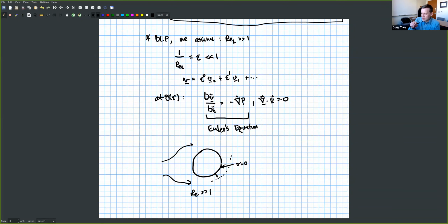And in cylindrical geometry, you can see that this doesn't happen. We talked about this if you took my undergrad fluids class, and hopefully somewhere in fluids, about what's called D'Alembert's paradox. It turns out, and we'll talk about this in a second, that when you solve for this outer region and then try to calculate the drag force, it is 0. That's because there are no viscous forces acting anywhere, and it seems like you shouldn't get a drag of 0, but you do.